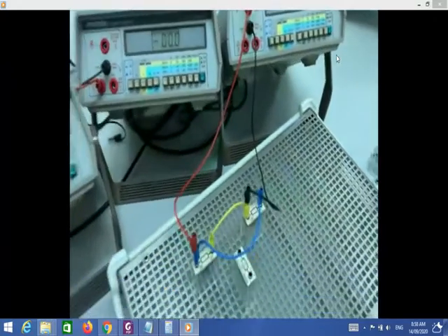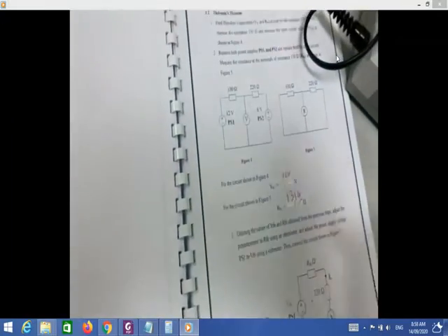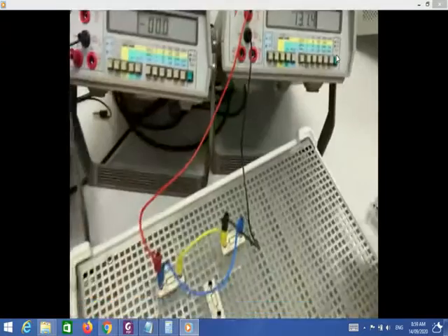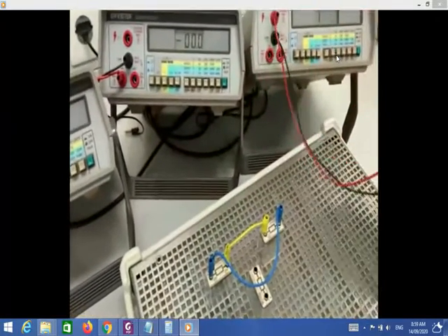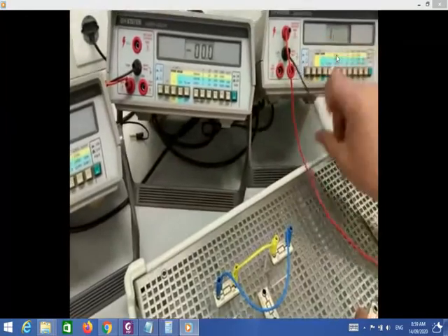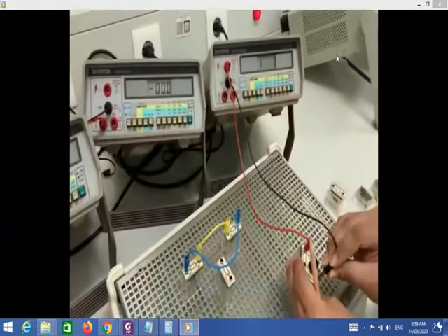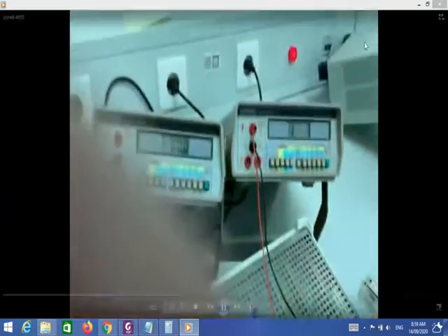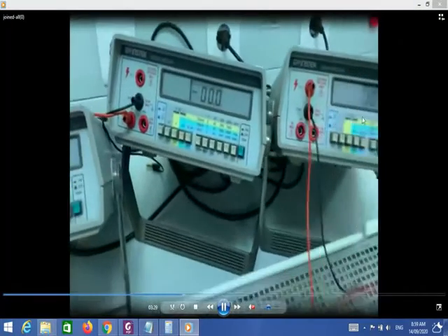Okay, so let us note down R Thevenin as 131.4. Now what we have to do is, we got V Thevenin as 10 volts and we got R Thevenin as 131.4. Now it's very simple: we have to take a potentiometer and set its resistance to 131.4, as we are doing here. We just check using the potentiometer.